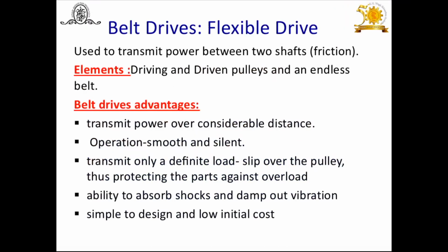Belt drives are flexible drives generally used to transmit power between two shafts by frictional grip or frictional resistance between the pulley and the belt. When there is a proper frictional grip, then and only then is power transmitted from the driving pulley to the driven pulley.